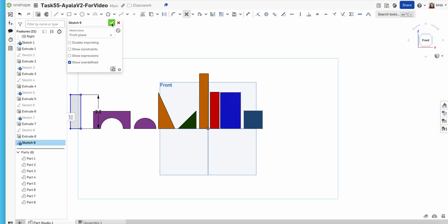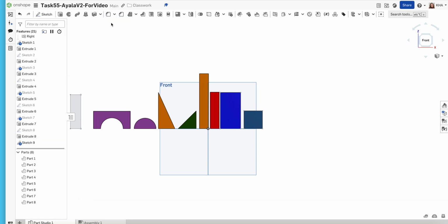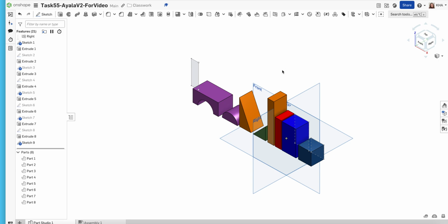This is basically a rectangle that has the height of our cylinder and half of the diameter of the cylinder, which is actually equal to the radius, right? So in order to make this rectangular shape into a 3-dimensional model, we're going to use the revolve.